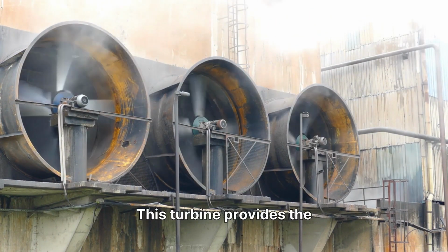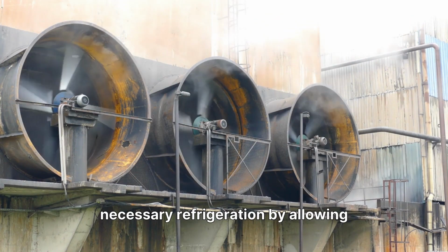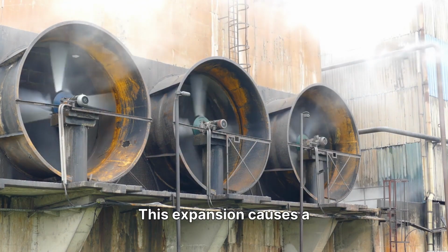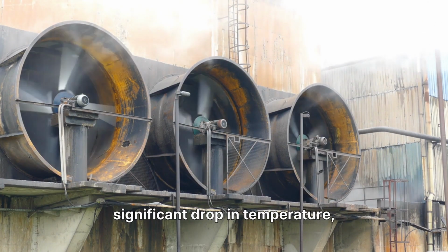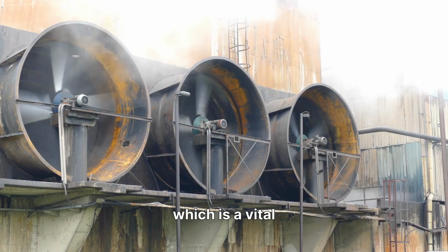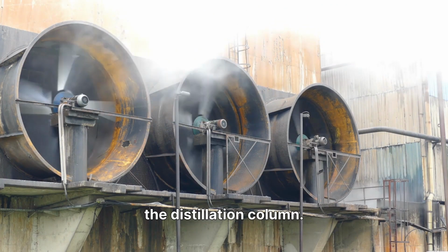This turbine provides the necessary refrigeration by allowing a portion of the air to expand rapidly. This expansion causes a significant drop in temperature, leading to the partial condensation of the air, which is a vital step before it enters the distillation column.